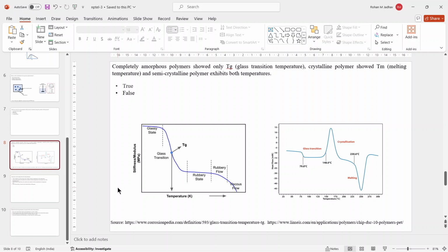Reducing the range of the melting point of the polymer is actually quite difficult. Why? Because you will need to increase the crystallinity quite a bit. You will need to make the polymer in such a way that it will only have sufficient energy for the molecules to move around at that particular temperature. You can crystallize it in repeated cycles. You can do that for a thermoplastic polymer, but I'm not sure it will work, because the molecules themselves will have that kind of tendency to move around at that particular temperature or range. So that's why, yeah.